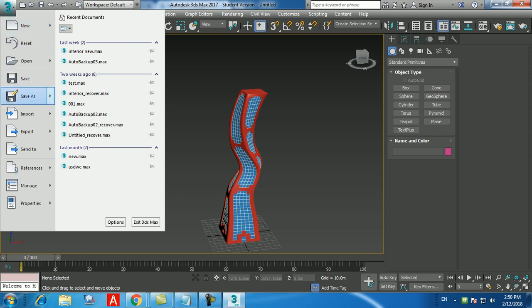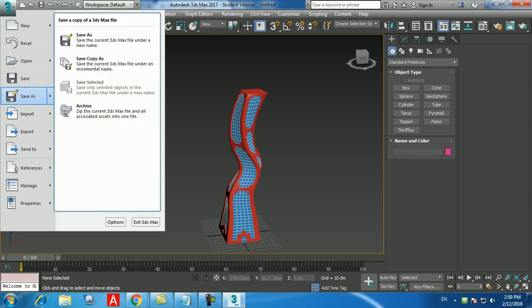So what is the difference between Revit and AutoCAD? AutoCAD doesn't help you to achieve BIM. Revit helps you to achieve BIM. Only this difference. Which means in AutoCAD, you are creating plan, you are creating elevation, you are creating section. Revit does it for you. You are just creating the plan. You get the elevation, you get the section, you get the 3D view immediately. You don't have to do anything.